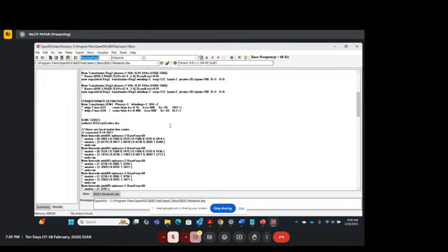So this is what's called the primary and secondary distribution system. On the primary distribution system you have the 4.16 kV level, right? And then you have this transformer. This transformer can be thought of as a service transformer or like a house transformer, which brings the 4.16 kV to 480 volts.